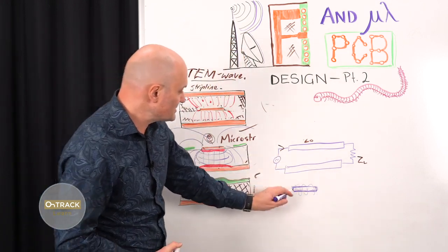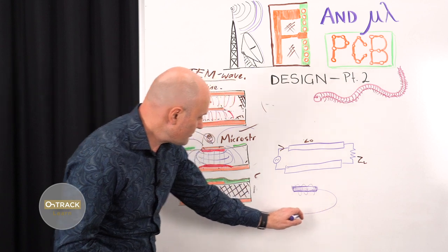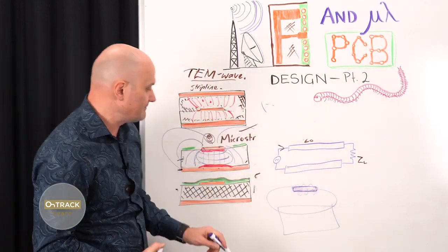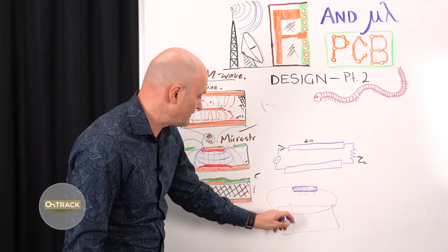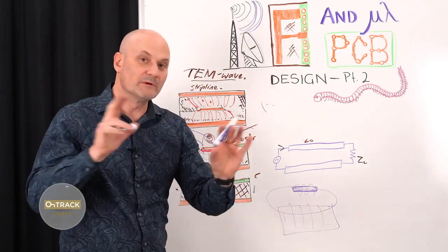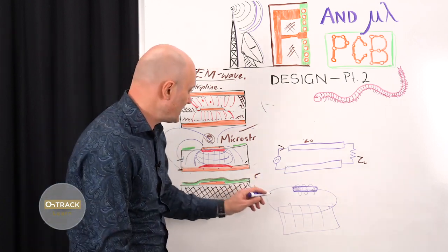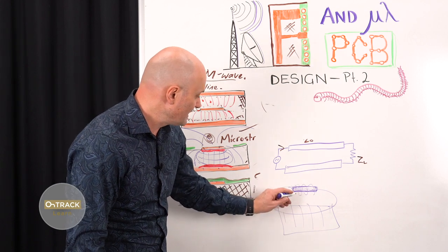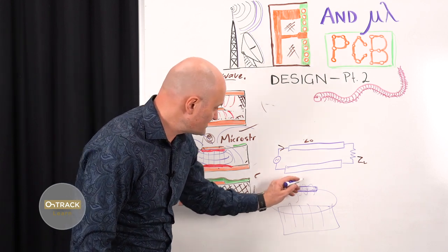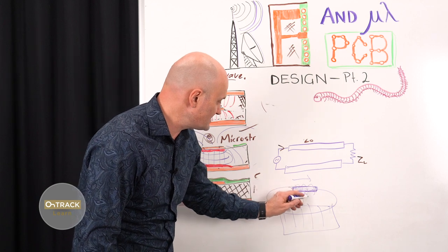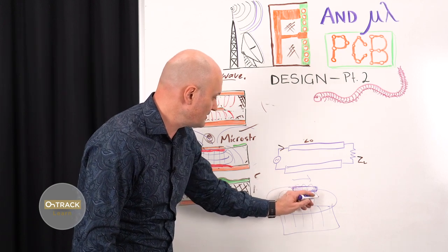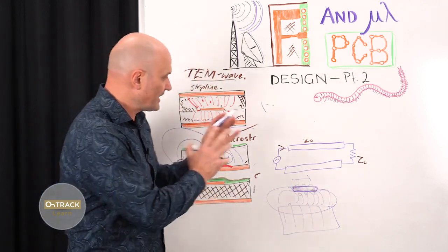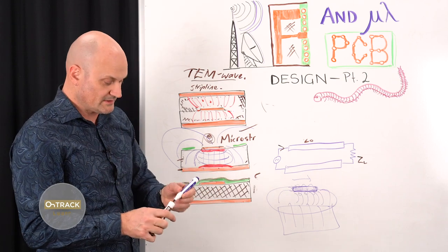Also, the transmission line, we know current has to flow in loops, and in a PCB, particularly at high frequencies, we have a reference plane, which is presumably at 0 volts, and then we apply an AC signal to our transmission line, and as it travels down the line, it has to charge up the capacitance between the PCB trace and the ground plane, and then it gets to the load, and that energy is transferred to the load like a bucket brigade delay line.